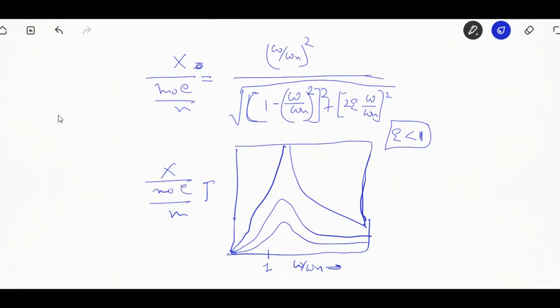Okay. Now a similar thing we can talk of for a reciprocating part, right? So the equivalent mass will remain the same situation. Consider an IC engine in which the piston, through the connecting rod, connects with the crankshaft and it starts to rotate. So the unbalance which we are supposed to have is in the piston part, right?